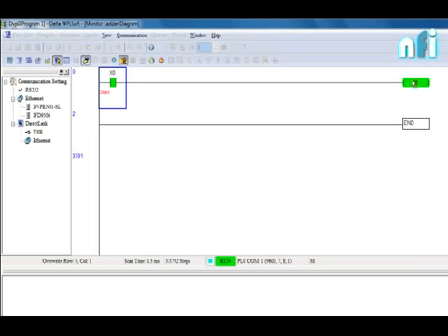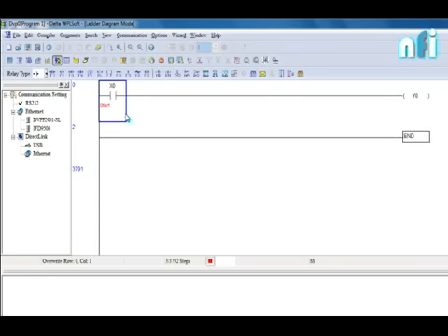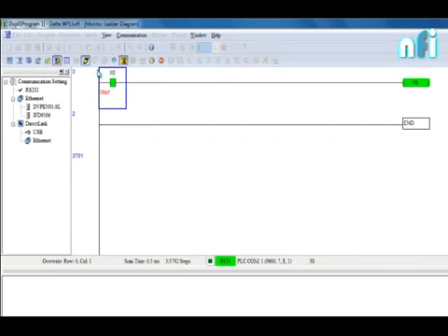That output I can see by the screen light here. So this is how we can get the indication from the PLC into the software. That indication I won't get if I go to offline mode. Now my X0 is on in my trainer, but it is not shown here because I'm in the offline mode. To go back to the online mode, I have to go here like this.